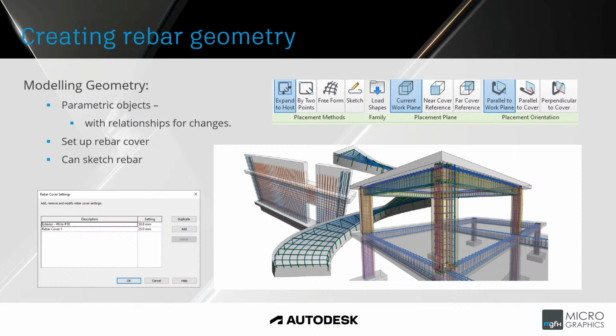So by sketching it, it's not just a random sketch. Revit will start recognizing the shape of the sketch as you make it. On the bottom left is just an example of the rebar cover settings, and you can describe the particular cover, and also give it a dimension.